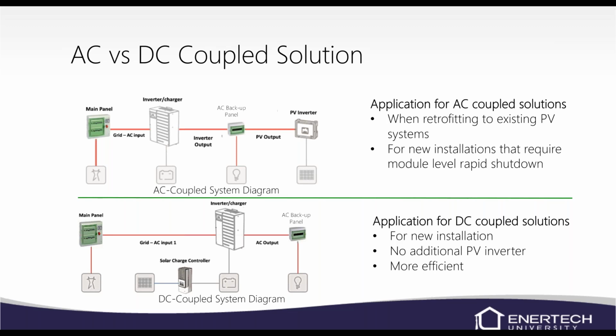But the Solarc inverter and the Fortress battery setup can do either one, but it's best if we can start with a PV coupled system, that would be, quote unquote, a new construction application. Another note that I'll add is that if you have microinverters, you can only have an AC coupled system. And I think that's all I wanted to add on that one.